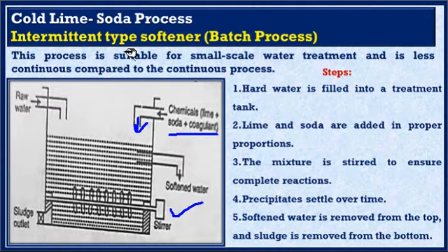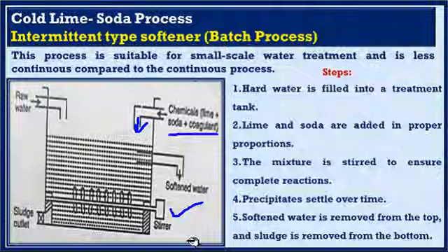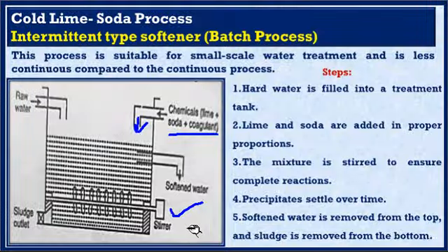So by the time the tank fills up, the reaction is complete and thus stirring is stopped, and the precipitate is allowed to settle down at the room temperature. The precipitate formed is finely divided, hence a small amount of coagulant like sodium metaluminate or aluminum sulfate may be added to this water sample so that the precipitate can easily settle down.